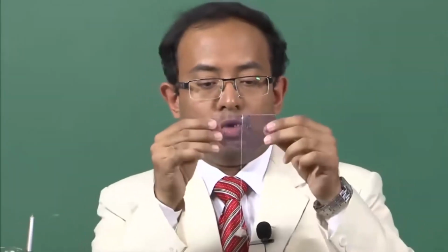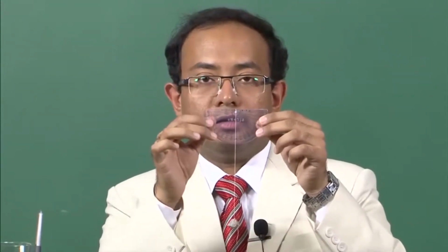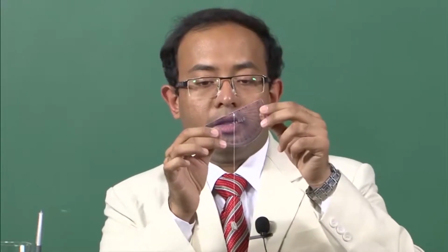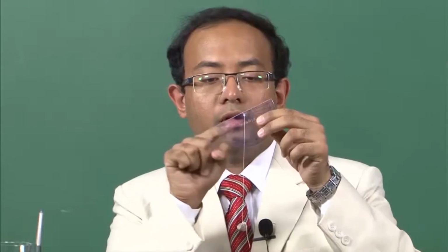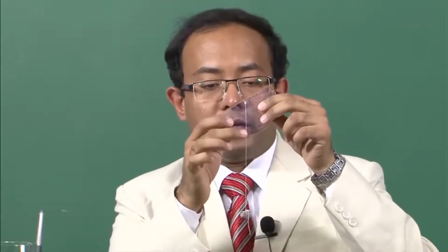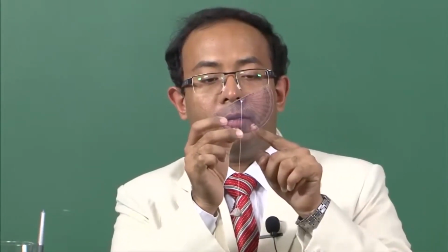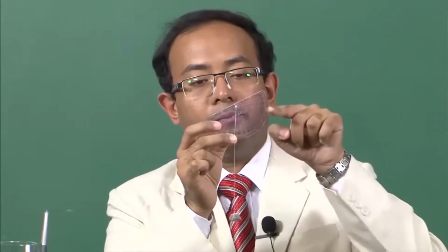so now when I am holding it like this, you can see that this angle is coming out to be 90 degrees. So now if you want to measure the elevation of some point, so when we turn it like this, then the angle that we are interested in measuring is this angle. So how can we reach to that angle? Well, we can directly measure that this point, it now says 120 degrees. So we can measure 120 degrees minus 90 degrees, which would give us this angle.